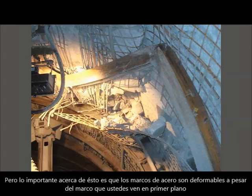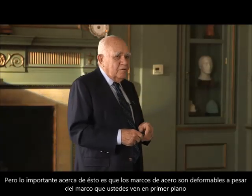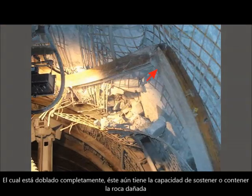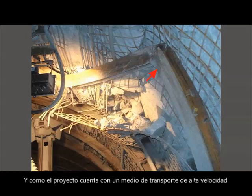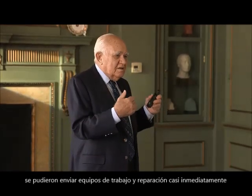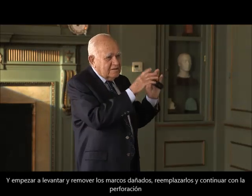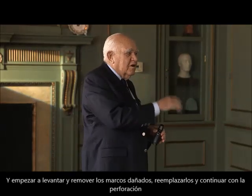But the important thing about this is that the steel sets are deformable. So in spite of the fact that this one in the foreground is bent right out of shape, it still has capacity to keep the damaged rock back. And so because they had high-speed transportation, they could bring their crews in almost immediately and start cleaning up, and they simply remove the damaged sets, replace them, and open the ground up.